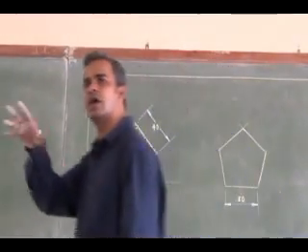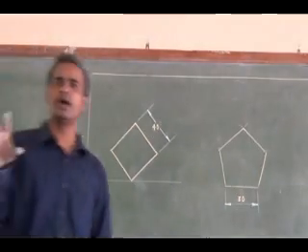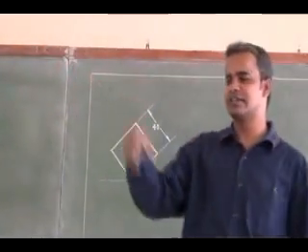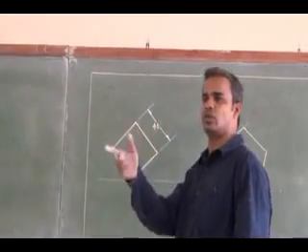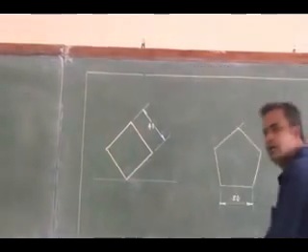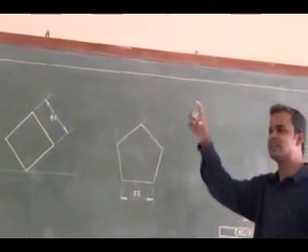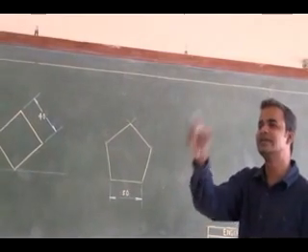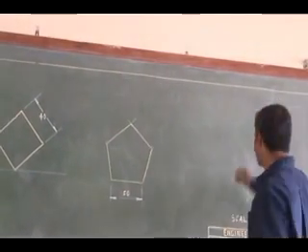Is it construction work, or what I want? I want a hexagon. The circle I am going to draw is construction work, so you have to use a 2H pencil. The radius of the circle is equal to the side of the hexagon.